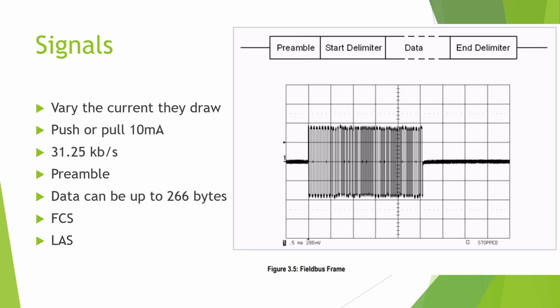If you actually think about your standard multimeter, that is only ever measuring voltage, even though it does current, it does distance, it does all these things. It's really only ever measuring voltage, and it's using Ohm's law to do that. You want to measure a resistor, so I am going to supply 5 volts at 10 milliamps or whatever the magic that multimeter is using, and it measures the voltage drop across that resistor. And it's able to do the math to say, if the voltage drop at 10 milliamps is this, that means the resistance is this, and it shows you on that screen. So it's only ever measuring voltage.